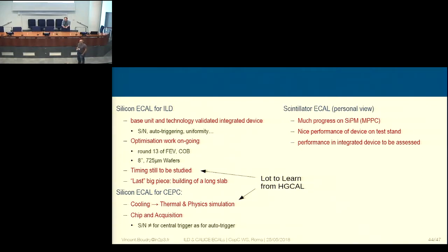Okay, yeah. Then the final question, your comment about the silicon photomultiplier response. Obviously, you're testing and qualifying with a strontium source or whatever radioactive source. So you're actually working in self-trigger mode. But as long as you work in sync mode, then the problem of the low detection and the DCR is gone. Not completely gone, but very much reduced. So again, the signal will be a lot cleaner because it's occasional and random, and if you scale it up, the probability that you have a pile up overlay to your signal is very small.